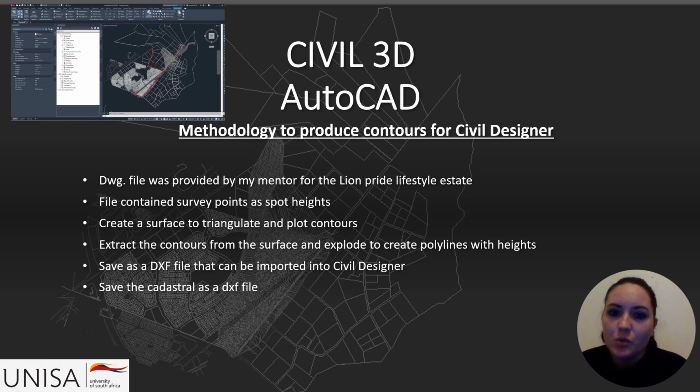But in order to get these contours into Civil Designer, you would need to extract the contours from the surface created and explode them to create polylines with heights. Then you need to save the polylines as a DXF file, which can be imported into Civil Designer. I also saved the cadastral as a DXF file so that when using Civil Designer, the ease of reference is more clear.